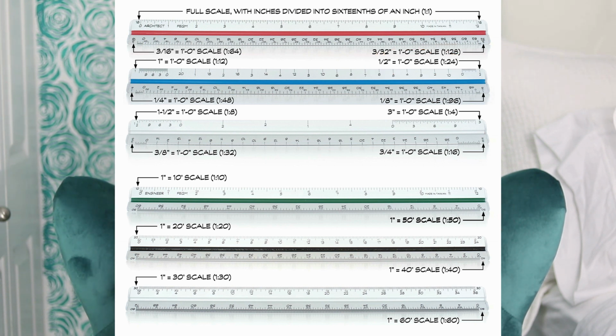It could be a larger piece of paper that would tell me, okay, actually this wall is 11 feet, and now I know. So when you have that measurement, even if you only have one measurement of one wall, you're actually able to measure out everything else as long as it's drawn, because you now know this is the measurement I'm working with. If something is this big, it actually is referring to something that is this big. So you measure how big the window is or how big the doorway is, and you're able to know, okay, this is 1/2 an inch technically on this ruler, but what it means is it's a foot. So each 1/2 an inch equals 1 foot.